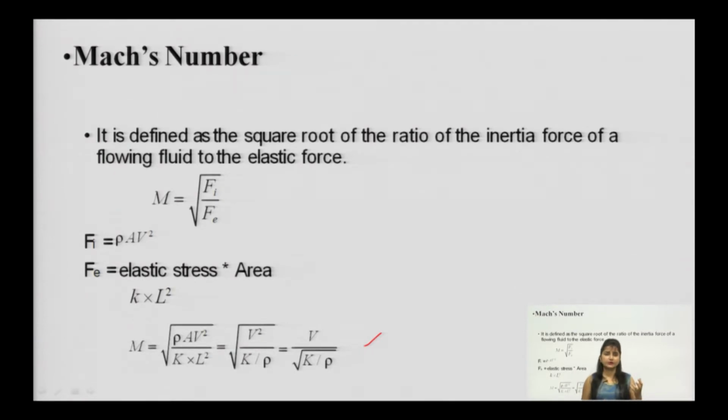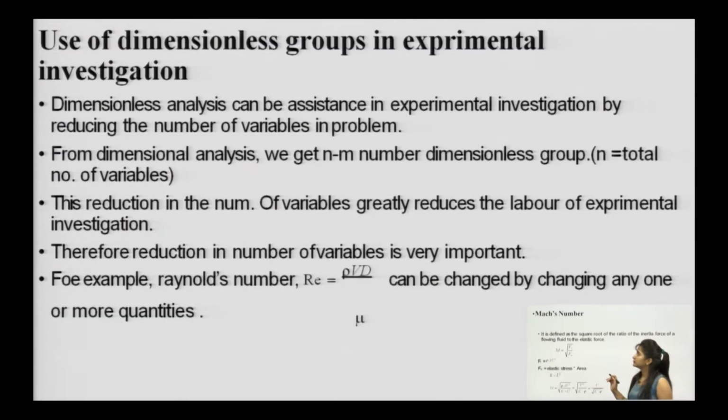So, these were the mathematical relationships which you found out with the help of Newton's second law, where total force is equivalent to force due to gravity, force due to pressure, force due to viscosity, force due to compressibility, force due to turbulence, and force due to surface tension. This is the main equation. Here we have categorized certain ratios and named the constant terms like Mach number, Euler's number, Weber's number, Froude's number, and Reynolds number.